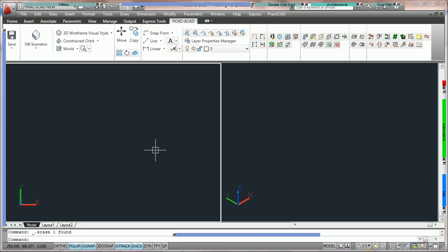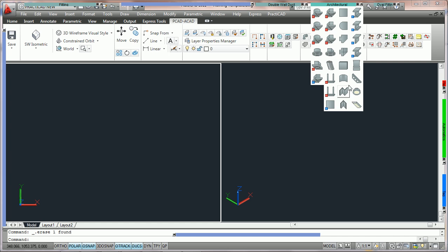The last wall type is the custom wall. The custom wall is the most flexible of all four walls, and actually the custom wall can mimic the same properties as the other walls. So generally I just leave the custom wall icon in the architectural bin and I never use the other ones. However, it's up to the individual draftsman to choose which ones work for you.